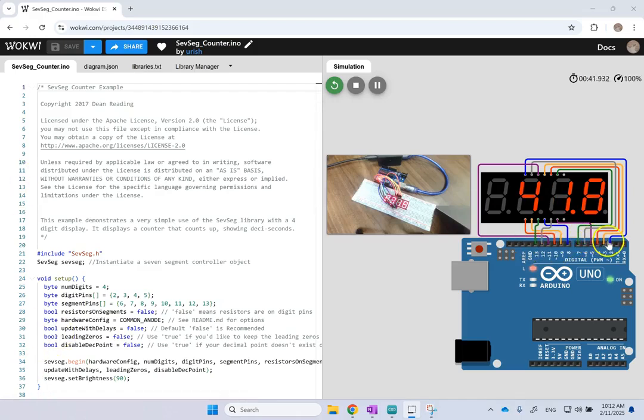And in here, no pin is directly connected with resistors. It should be ideally, but here for simplicity, I guess they did not put the resistors on. But if you want to limit your current and not burn that 7 segments in short time, you better put some 200 to 300 ohms on the way of each one of these pins. Okay, otherwise you can burn it in short time. But here, just for simplicity, it didn't do it, I didn't do it, but it's not a good practice.